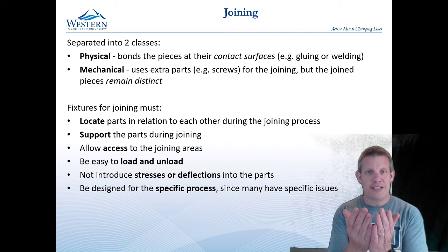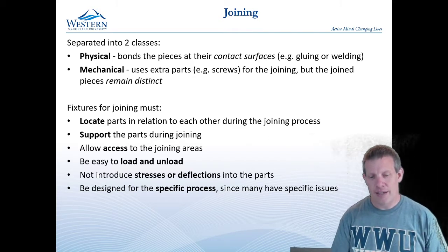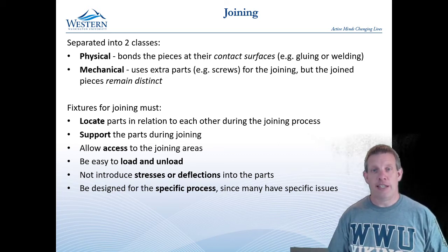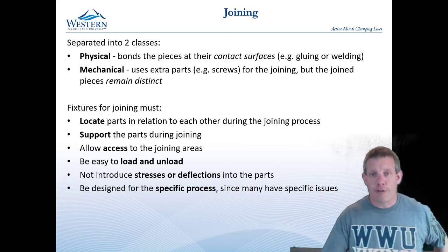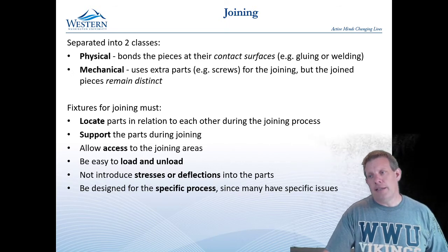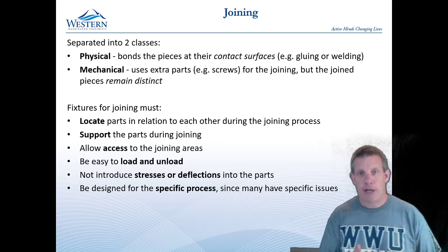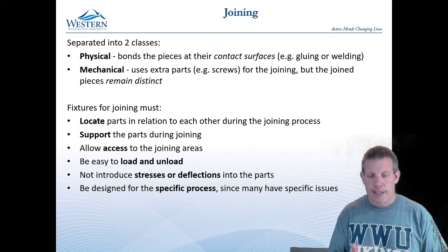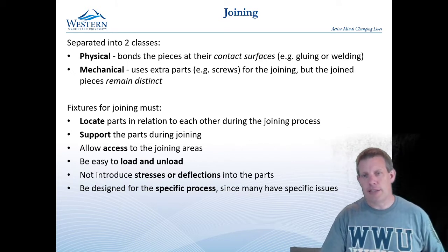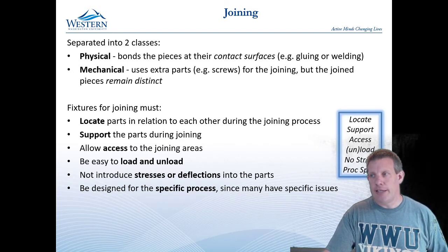Often the big structure is still kind of wobbly because you have to put it in for another assembly operation maybe. And so loading and unloading is really complex, and that is often one of the biggest challenges. And then anything for the specific process, so not damaging the part if it's pre-painted, dealing with chips, dealing with glue over squeeze, all kinds of things like that, dealing with the heat that's in welding. Those are all really important to understand.